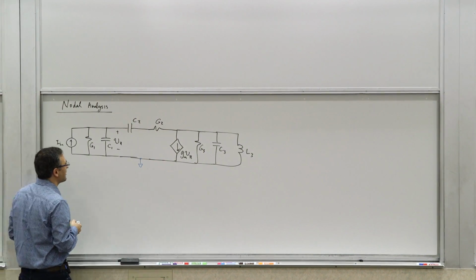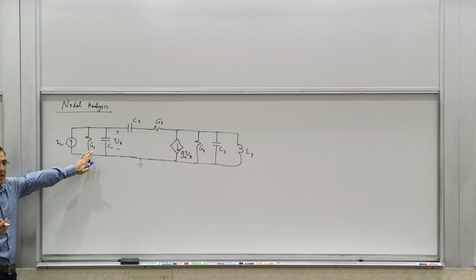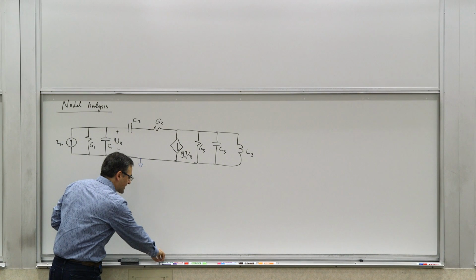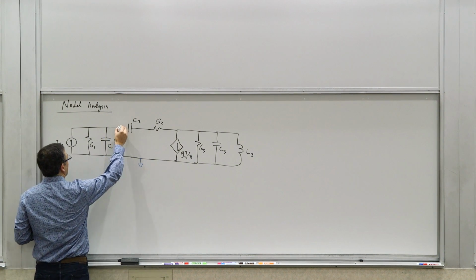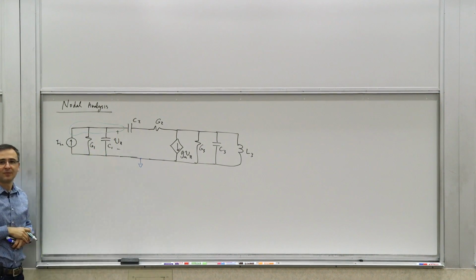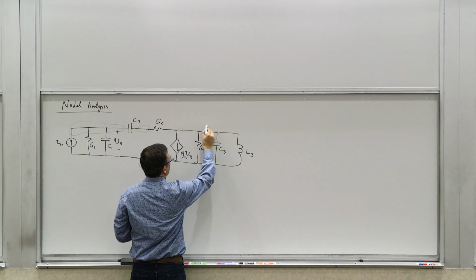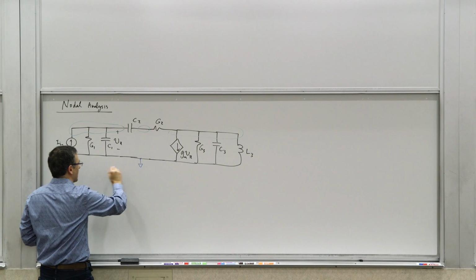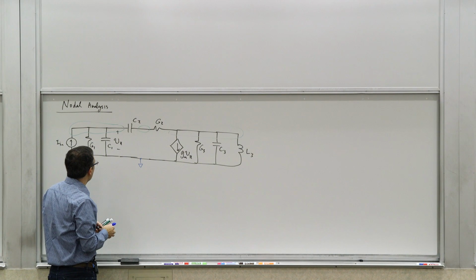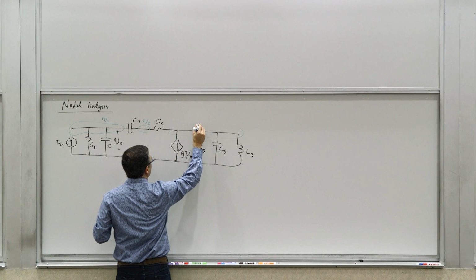So we define one potential as ground, or 0. So let's say your circuit has n plus 1 nodes. So now you're left with n nodes. In this case, how many nodes do we have? What are nodes? Nodes are defined as connected metals or conductors. So for example, this whole thing is a node, right? Or in that case, this is a node, or this is a node, and this whole thing was a node, right? We defined it. Now, we define a voltage for each one of the nodes. So we call this, for example, V1, the voltage here, V2, and V3.